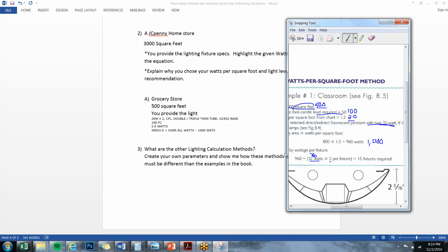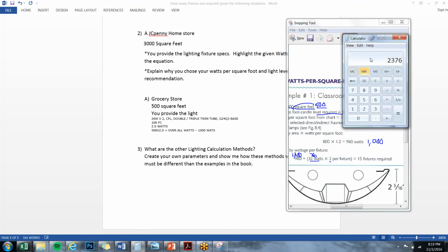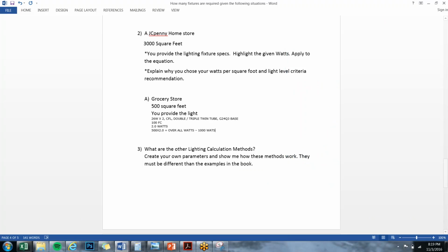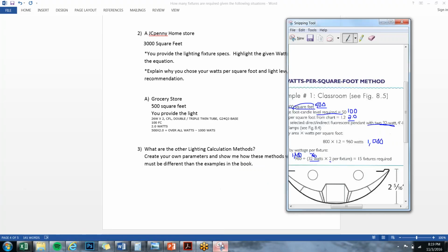So it's going to be 1,000 overall wattage divided by, in brackets, 26 times 2, and then that'll give us our fixtures. 52, you say? All right, so Emily does math for us in the background, and it magically makes it all come out to be 52 fixtures.